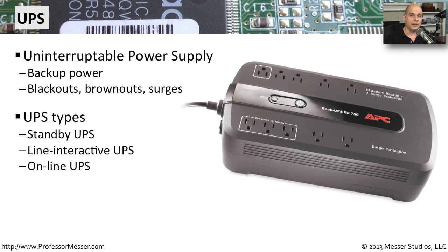Even though it's very short, you'll sometimes find equipment that can't handle the time involved for the switchover from the primary power source to the backup batteries. Because of that, you'll often find line interactive UPSs. This is not a standby UPS, but it is able to slowly move over to battery power if the line begins losing power, browning out, or having any type of problem.